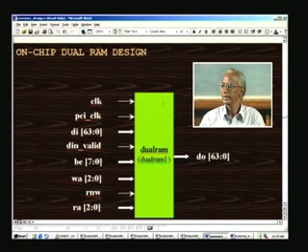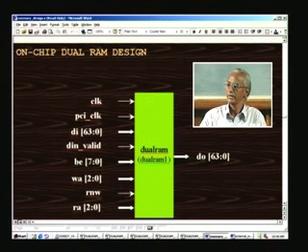And here as I mentioned before, we will be writing into one of the RAMs, and in order to write what we need is a separate input here. It should be 8 bytes in width, that is 64 bits, and this is the PCI compatible input bus through which we will be writing the actual image data.